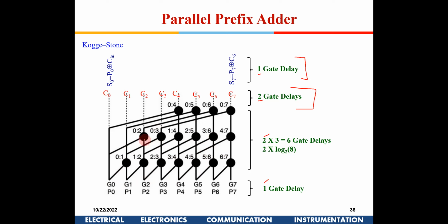All of this is hardware consisting of 3 gates which combines G0 P0 and G1 P1, and this is hardware which combines G1 P1 and G2 P2, right. But for carry 2 I require everything together. So I require one more dot operator out here. Is it okay with all of you?